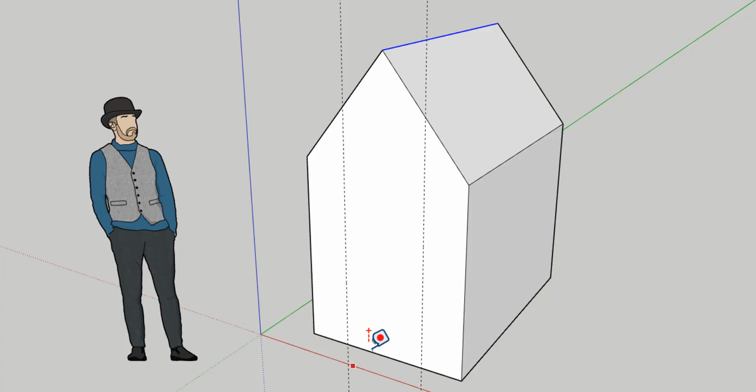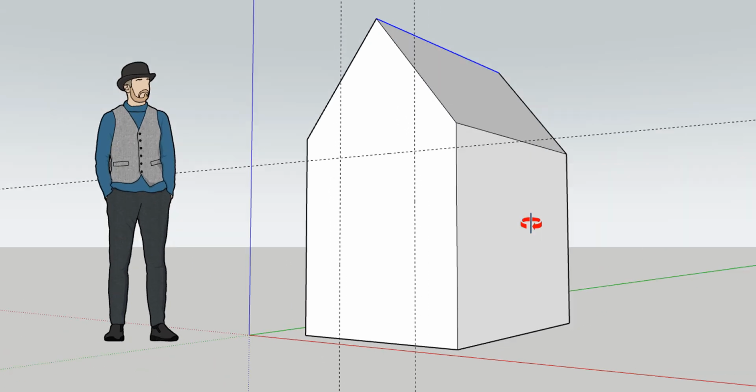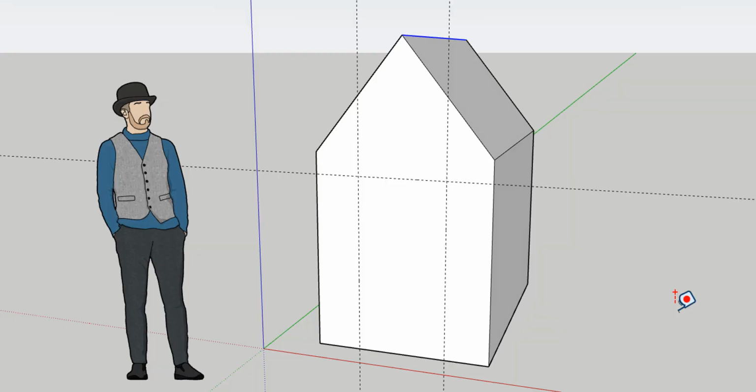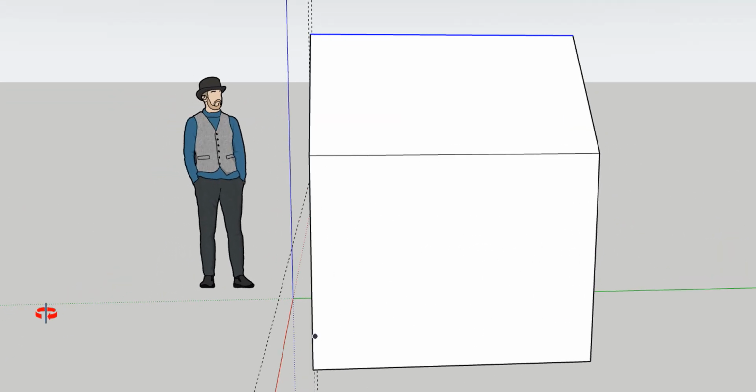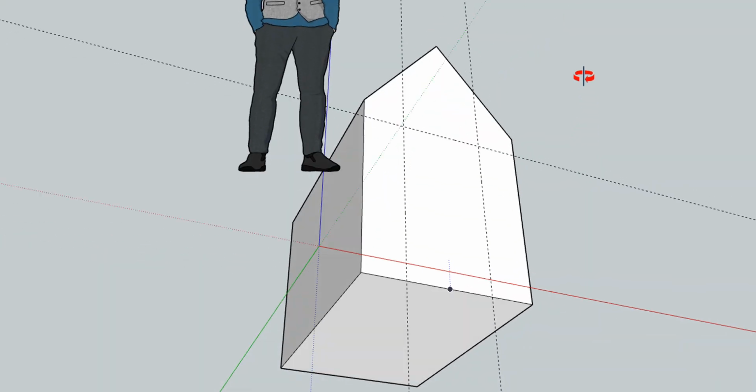And then from the bottom up, again, I'm going to go from the bottom up, and I'm going to try and stay away from the midpoint. Again, sometimes the midpoint creates different kinds of lines. Click, go up, type in 48, and now I've got a location that I can snap to. Now I went straight up, I went straight across. So that made it sure. If you orbit, remember, hold down the scroll wheel and you can orbit.